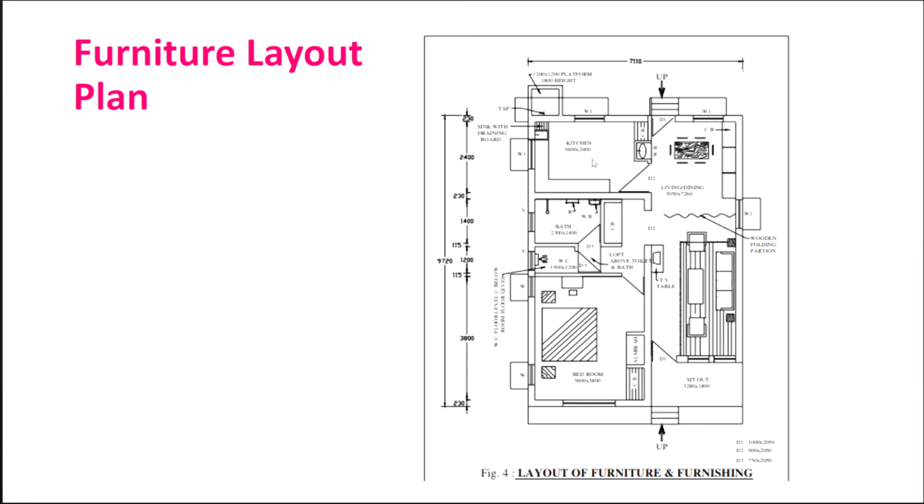Most important, we never make this furniture layout plan. And I suppose everybody agrees that we are never making a furniture layout plan. You must have seen in various rest houses or quarters, although I may be planning, as you can see in this area, this is a bedroom, you may be providing a fan at the center of the room, because normally it is our practice. But the bed is somewhat on the side of the wall, and many times we don't have the fan in the right location. So in case I have frozen my furniture layout plan, I can plan electrical installations and other things